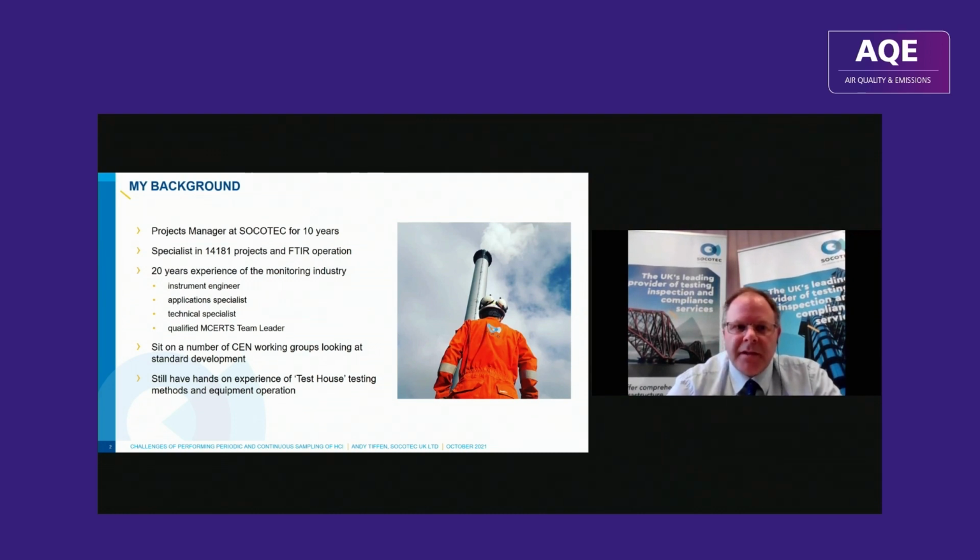Predominantly over the last few years, looking at 14181 projects, calibration of CEM systems for HCl. And as it says on there, I'm still an MCERTS team leader, so I still have the joy of heading out on site and seeing this work being done in the field as well. So some of the actual real life practicalities of what the guys need to do on site in order to get a reliable result, the best result that we can get for HCl measurement.